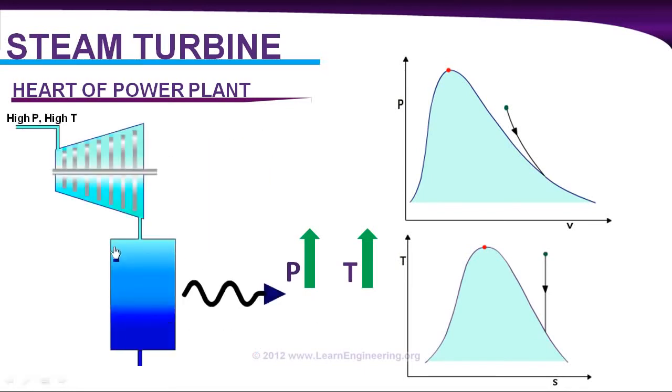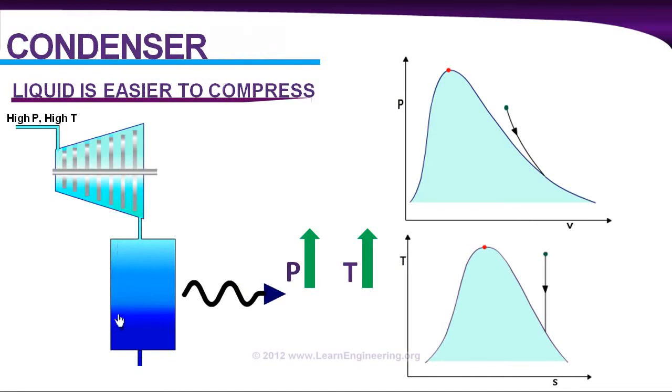Like this. You put a condenser over here that can reject heat to the surroundings. So vapor will get transferred into liquid state. Now this process can be drawn in PV and TS diagram like this. And during heat rejection there is no pressure change because fluid is free to expand. And obviously this is a phase change, so temperature cannot change. So this is in TS diagram. Now the fluid is in liquid state.